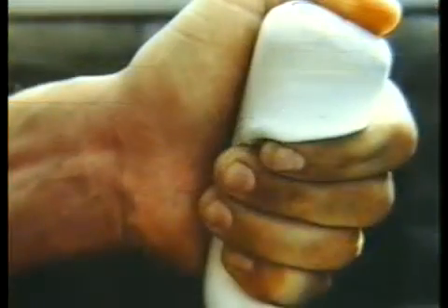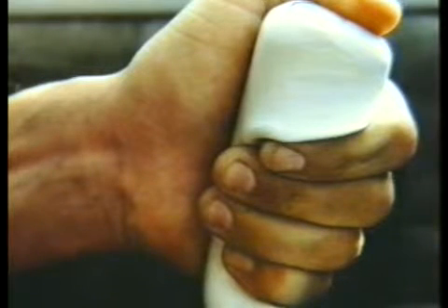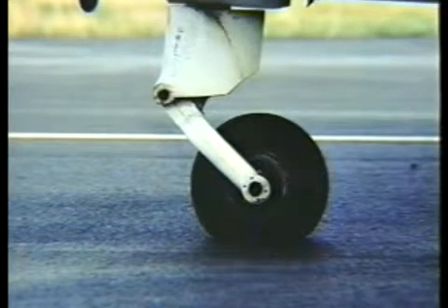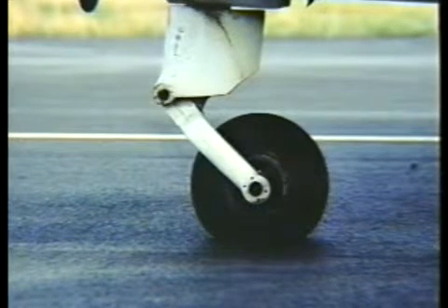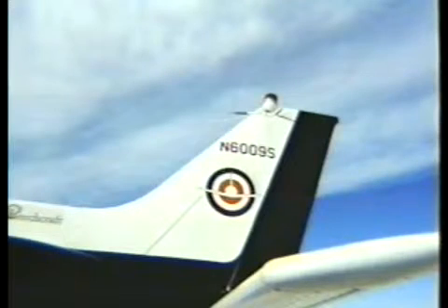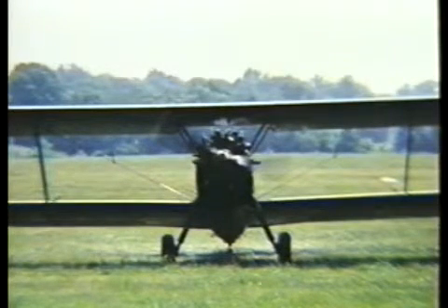Once the nose wheel is on the runway, the safest way to increase braking effectiveness is to hold the wheel or stick full back as you firmly and smoothly apply the brakes. Back pressure is held primarily because, with heavy braking, the airplane tends to lean forward, putting a greater portion of the weight on the nose wheel. Use of up elevator or stabilator counters this reaction and puts weight back on the main braking wheels where it belongs. In tail draggers, it also reduces the chances of dinging the prop or flipping over as you brake.